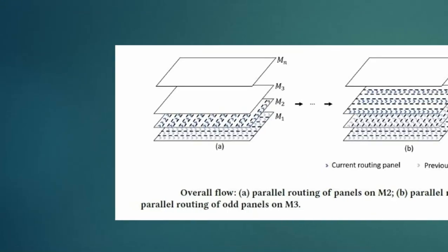Yeah. So if you see now, each of these layers, let's focus on, let's say, metal 2. So metal 2, the proper routing direction, in our case we have assumed it to be vertical. So that's why these dashed lines are actually vertical. These dashed lines are nothing but what are called panels. And each routing guide is assigned to one panel.